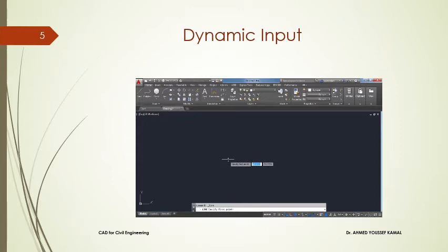And when you move your cursor, you'll see that x and y coordinates of this point or the current position changes. Let's click at this point. Now since we have clicked, you'll see that the values now change, and now you can see a distance. So this will be the distance of this line, which you can see in the first box. So in this case, let's enter the distance of 200 units. When you do so, this line will get locked to a distance of 200 units.